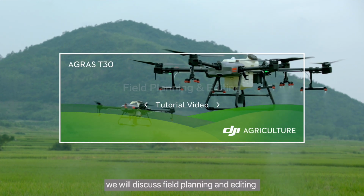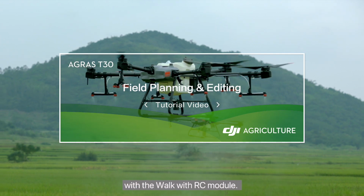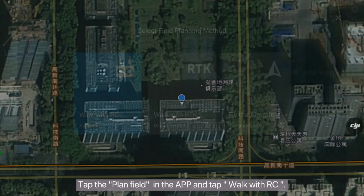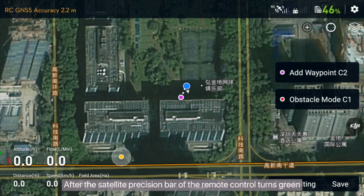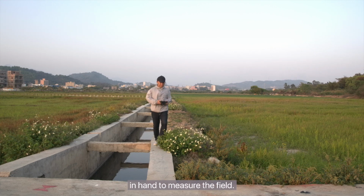In this section, we will discuss field planning and editing with the Walk with RC module. Tap the Plan field in the app and tap Walk with RC. After the satellite precision bar of the remote control turns green, walk along the field boundary with the remote control in hand to measure the field.